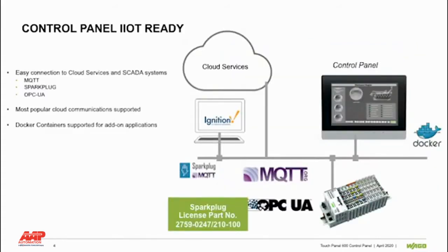An advantage of the Wago Cloud panel is that it is IIoT ready. Much like Wago's PFC200 platform, this device supports protocols that are utilized by most cloud services such as MQTT. Many cloud applications leverage the advantages of the lightweight MQTT protocol, so it is very easy to exchange data directly from the control panel to your favorite cloud.